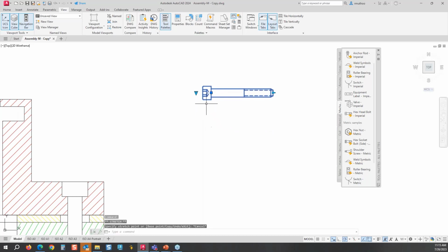And then we also have the list grip, which is indicated by this small downward-turned arrow and a line above it. As we hover the cursor, it turns red. But at this point, we have to click it, and you can see the different options that are available. And these are the sizes for this bolt.